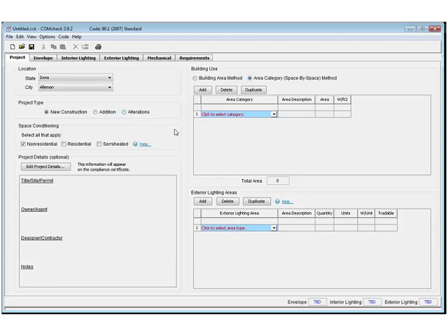Space conditioning. Select all that apply. This means you might have multiple spaces within a building. Maybe one story is non-res and the next story is high-rise multifamily units. And how this works is, as I mentioned again, I could have both of these. But when I go over to the Envelope tab, and I'm going to choose these two so we can play around with it, I want to define the applicable building envelope components that would fall under non-res versus the ones that are res. So if it's a 5-story building, then under the residential portion, I'm only going to put those exterior walls that reflect the residential part of that building.